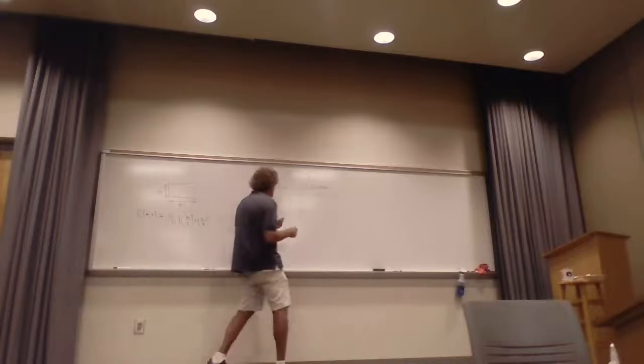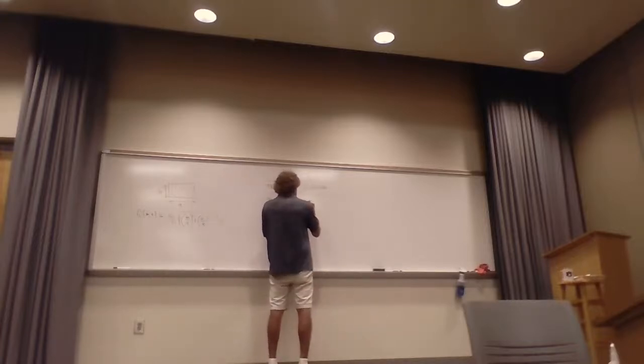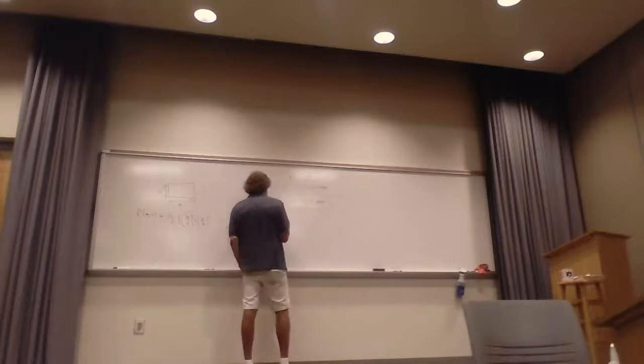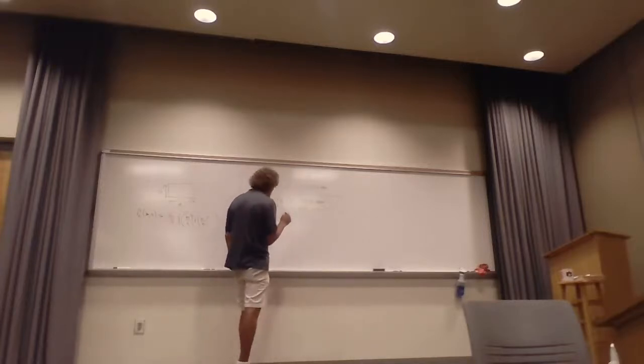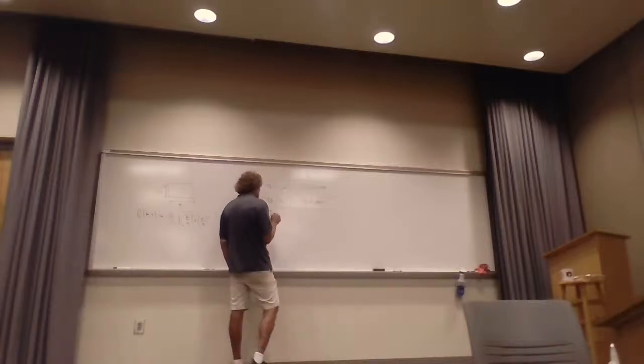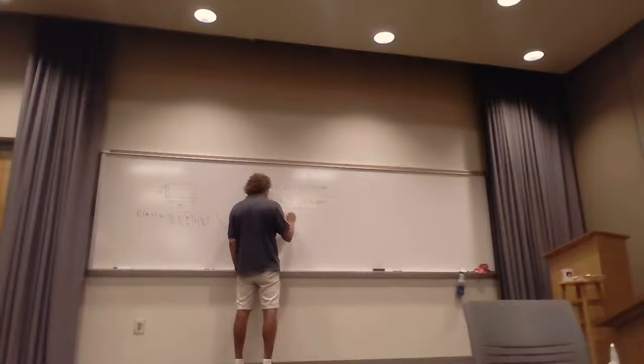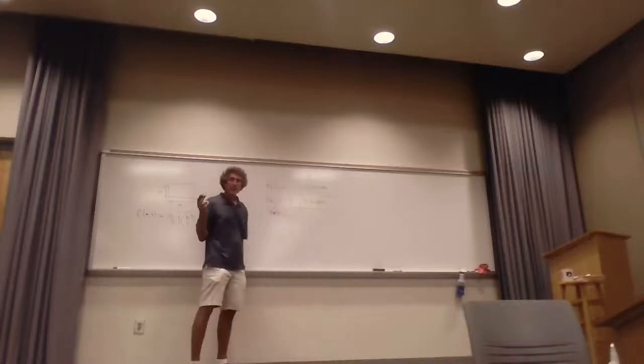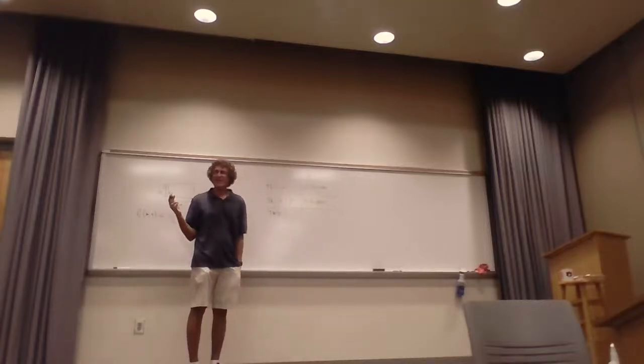So then it's the TE01, and that's 9 point, can you tell me what that is? 9.8 gigahertz. All right. Then after that, you're going to get the TM11 or TE11. Isn't that right? And that's 10 or 11 something?